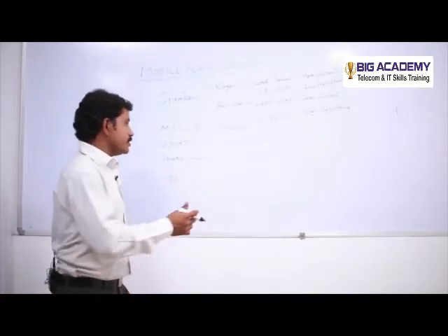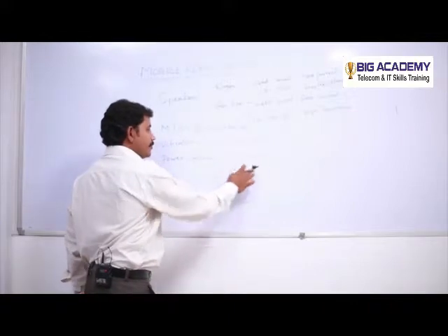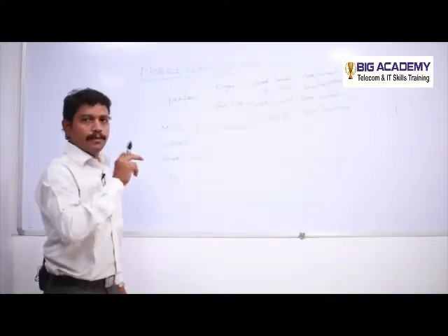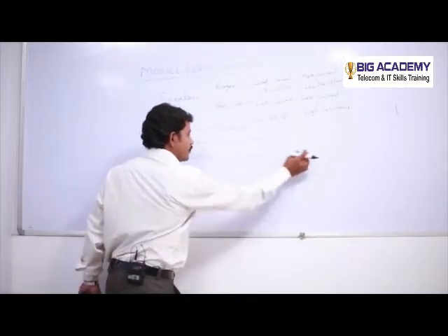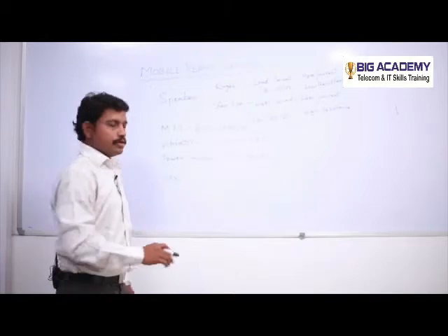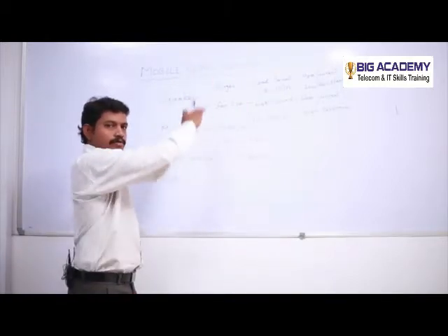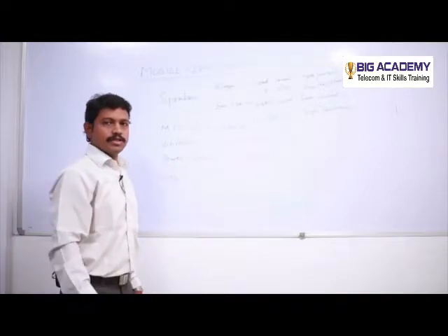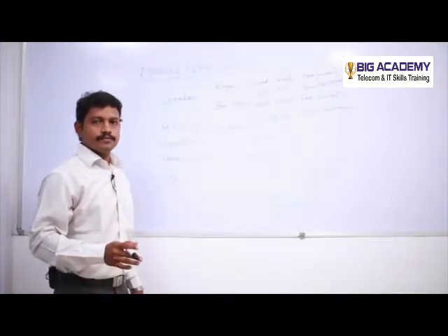If it is not giving the value in between this, the particular part is not working. Or if it is far away from the given value, higher or very lower, the power switch or the vibrator or speaker or whatever things are mentioned here may or may not work.